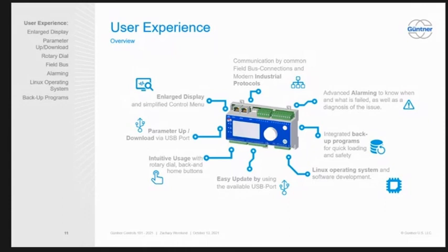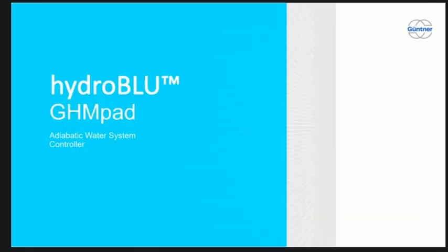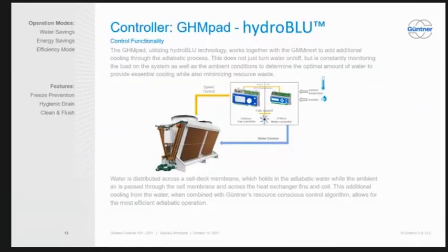That's exactly why, when you load one configuration from one controller to a next unit, you have to tell it the fan ID and the fan RPM. So that's one of the things it asks you for when you're loading it, let's say we go back to that example from a 12 fan unit to an 8 fan unit. It's going to ask you for the fan count, the fan row, the fan ID, and the fan RPM. And you put that in the controller, and the controller programs the fans. So now getting into the adiabatic side.